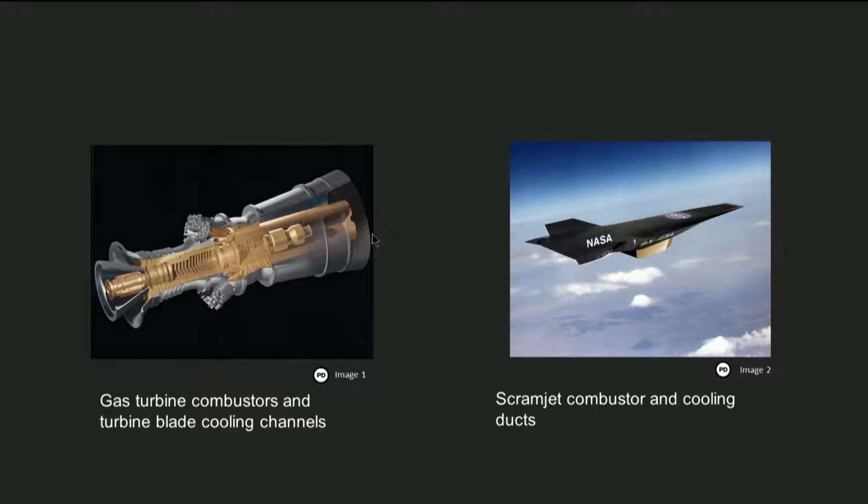For very high-speed scramjet engines, we know that we do not require the turbo machinery, that is the compressor and hence the turbine, to achieve compression. Here the air gets naturally compressed owing to the formation of shock waves. The rest of the cycle is very similar, that is, we have to add heat to the flow in the combustor and expand it via the nozzle to achieve thrust.